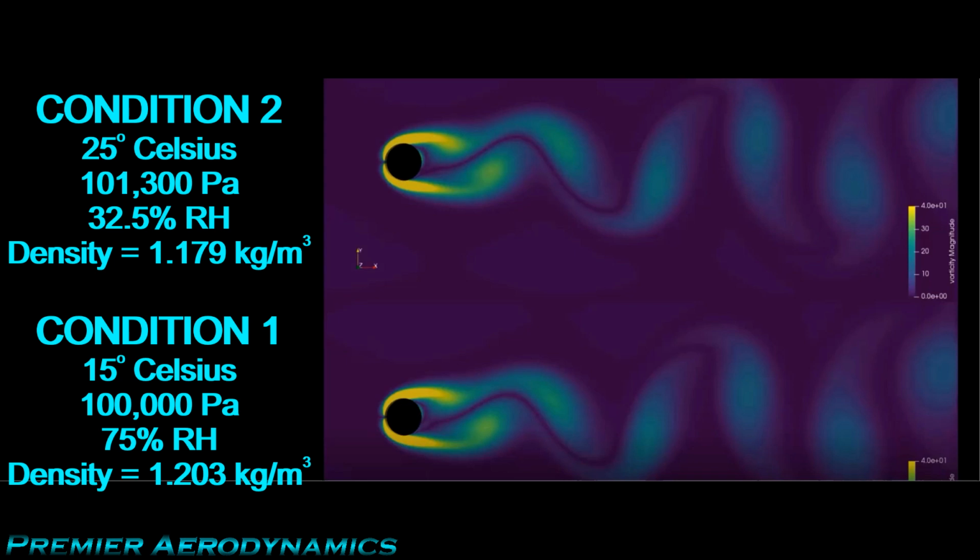Let's say inside your wind tunnel is now 25 degrees Celsius. And that's very common. That's about 80 degrees Fahrenheit. So 25 degrees Celsius is a typical operating temperature in a wind tunnel again, and that could be a spring day or later in the day or mid-morning or during midday in a summer day. And let's say the barometric pressure is 101.3 kilopascals, so the typical quintessential barometric pressure that we all use as an assumption, by the way, but it changes every day. It can change between